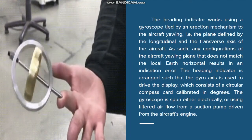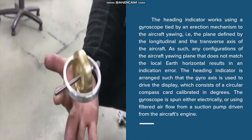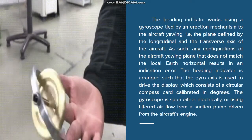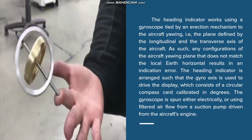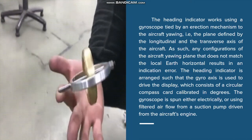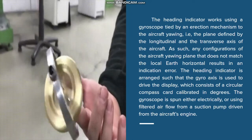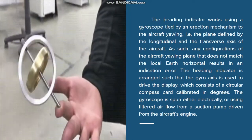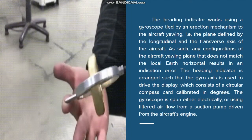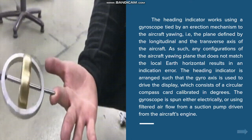As such, any configuration of the aircraft yawing plane that does not match the local Earth horizontal results in an indication error. The heading indicator is arranged such that the gyro axis is used to drive the display, which consists of a circular compass card calibrated in degrees. The gyroscope is spun either electrically or using filtered airflow from a suction pump driven from the aircraft's engine.